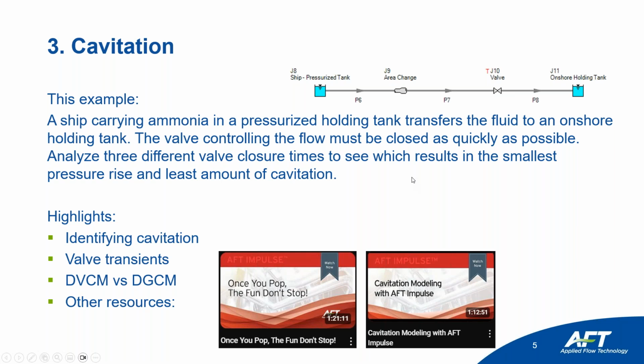However, if you are familiar with surge in any regard, you know that closing a valve really quickly can often lead to high pressure spikes and oftentimes cavitation as well. So we're going to go over this model and show you guys how closing this valve quickly creates pressure spikes and cavitation.